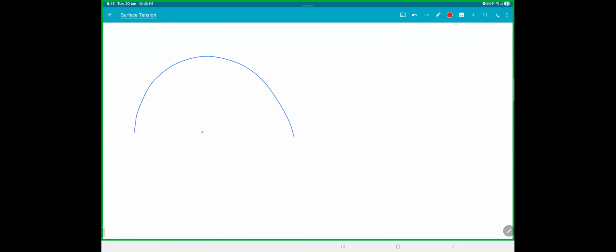So from the center, at an angle theta, take a thin piece d theta. I'll show you something even faster actually without doing this. So on this thin piece, this length will be r d theta. So your surface tension force will be along, it's pulling here. This will be the force, which is how much? S into length r d theta into 2 because there are two surfaces. That is the force. If that is theta, this is theta.